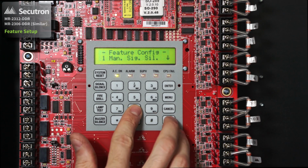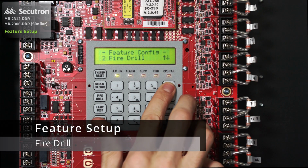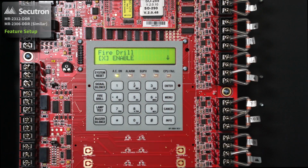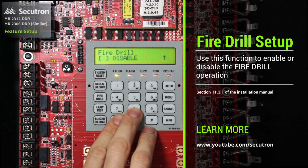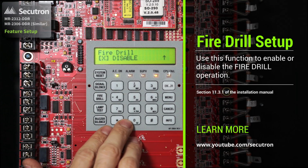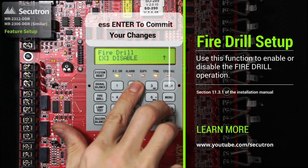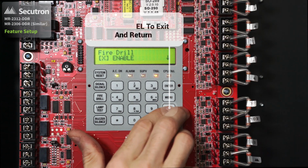The next feature up would be our fire drill. Same with this, we can select Enter. By default, it has been enabled. If we'd like to disable the fire drill feature, we press down and then again one of the left or right cursors to apply the X. Once it's been applied and the desired enable or disable has been selected, we can go back.